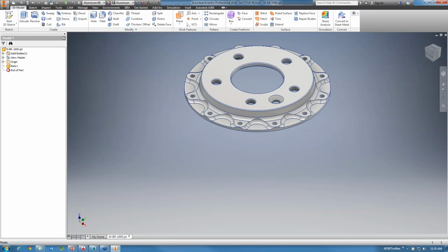And this is a key point around performance and usability. If you were working on a 100-part assembly or an XREF that had 20 XREFs and only 2 of those files had changed based on somebody else's design, you would only bring out those 2 files, because we do a checksum with your local workspace and Vault, and it's ultimately determining what deltas only need to get brought out. So it's really increasing the performance of file copy from the system out into Vault, and ultimately you're bringing out the files that you need, and you're working off your local, so it speeds up.